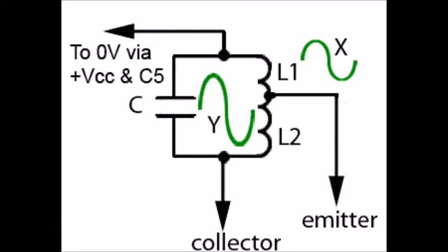So about the answer to this question, tuning into any of the frequencies, considering 93.5 Red FM, what we do is we basically change the variable capacitor through the tuner which is present on the exterior of the circuit. What that does is, since the frequency of resonance is 1 by 2 pi root LC, on changing the capacitor we can tune into the desired frequency, and the circuit is set for the same.